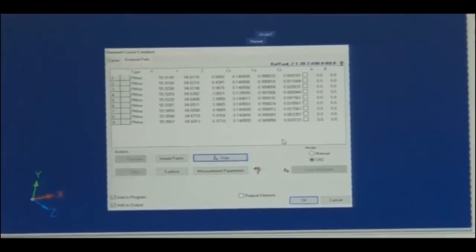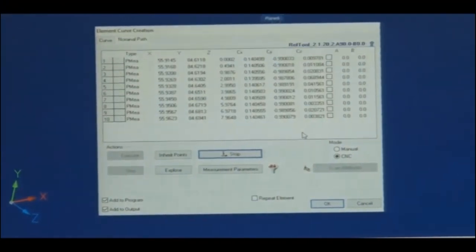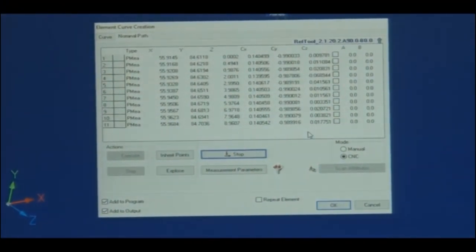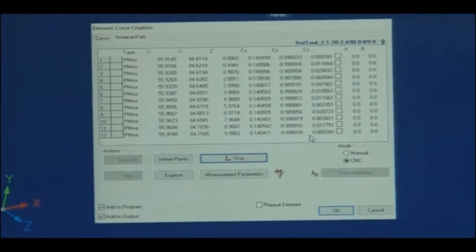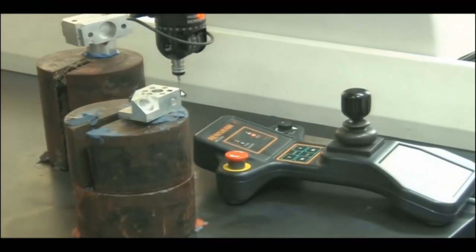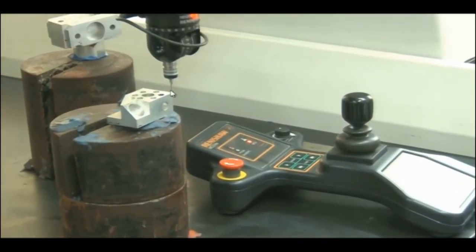It will keep recording unless it exceeds the x direction, where 500 mm is the length it can move. So, it can keep moving up to 500 mm, unless this workpiece finishes here, where it would not find anything.